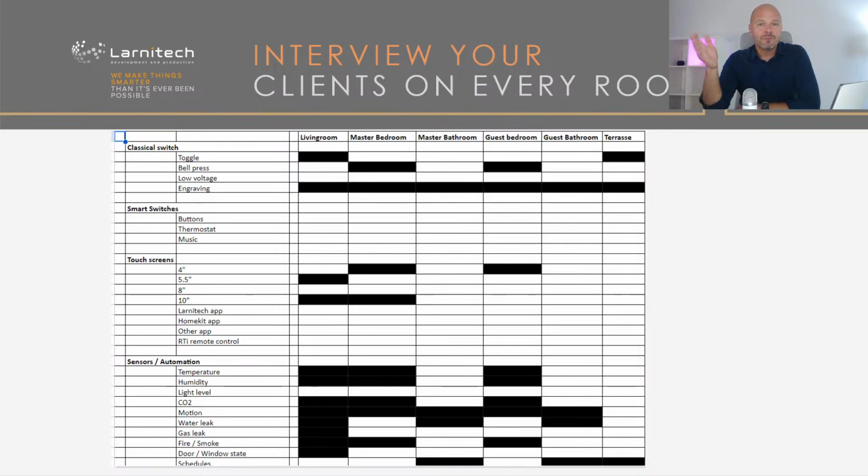And then start interviewing your clients with this table. We will send you the link to the folder in Google Docs where you will find this kind of table. So when you talk to the client, you tell him, okay, we are in your living room. What kind of control do you want there? Do you want a classical switch? He says yes. Do you want buttons, low voltage, or normal toggle switches? He says toggle switches. Do you want engraving? Yes, and so on. Do you want touch screens? Which size? Do you want automation with humidity, for example, in this room, and so on.